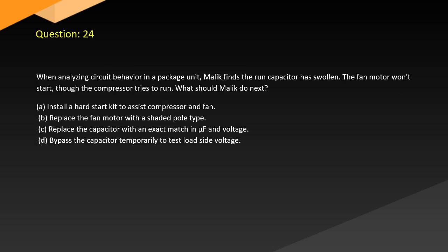Question 24. When analyzing circuit behavior in a package unit, Malik finds the run capacitor has swollen. The fan motor won't start, though the compressor tries to run. What should Malik do next? A. Install a hard start kit to assist compressor and fan. B. Replace the fan motor with a shaded pole type. C. Replace the capacitor with an exact match in microfarads and voltage. D. Bypass the capacitor temporarily to test load side voltage.